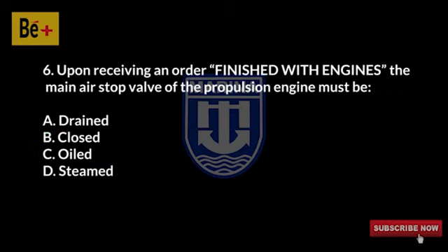Upon receiving an order finished with engines, the main air stop valve of the propulsion engine must be A. Drained, B. Closed, C. Oiled, D. Steamed. The answer is B. Closed.